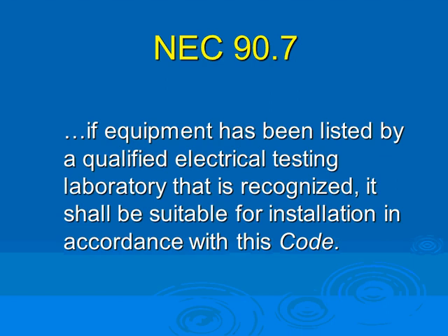So you've got a switchgear from China. No, you are not listed on it. You are not to design it and install it in your building. The only option you have, if you got it from China, from anywhere you want, the option that we have right now in Minnesota is you hire one of a bunch of engineers in Minnesota listed with the Department of Labor and Industry, recognized by the department, who can give you a signature or a report about a piece of equipment made in China that's not UL listed. When you get that report from the engineer, it's equivalent to a UL listing. There's a bunch of engineers who do that. It's really scary. You know, I'm not one of them. But you can hire an engineer basically if you have the equipment.